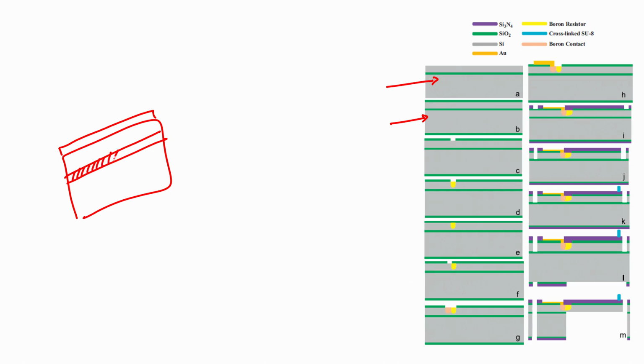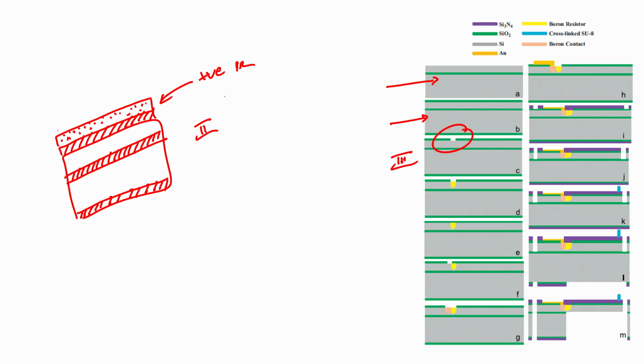This is silicon dioxide here, and silicon dioxide on the back side. So, this is our step number 2. What I am showing is how to reach step number 3, how to create this window. To create the window, you spin coat photoresist. So, I am spin coating my positive photoresist. The next step is you soft bake it at 90 degrees centigrade for 1 minute on a hot plate.